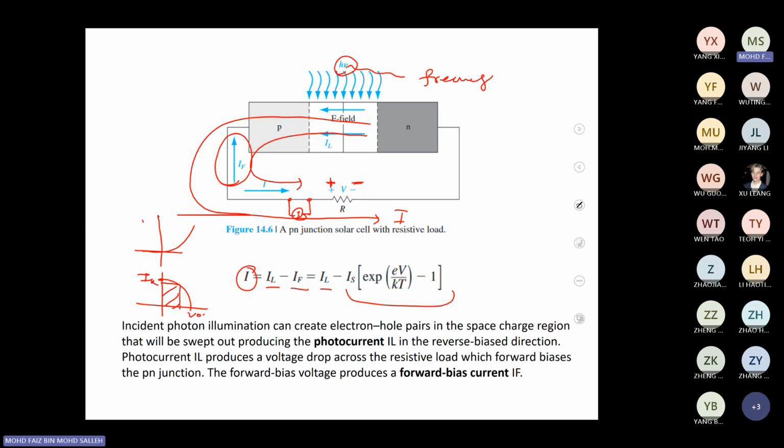So that's why we can have the equivalent circuit in terms of a diode over there, plus two kinds of resistance to consider the resistance of the contact and also the resistance due to the leakage or the defects inside the material.